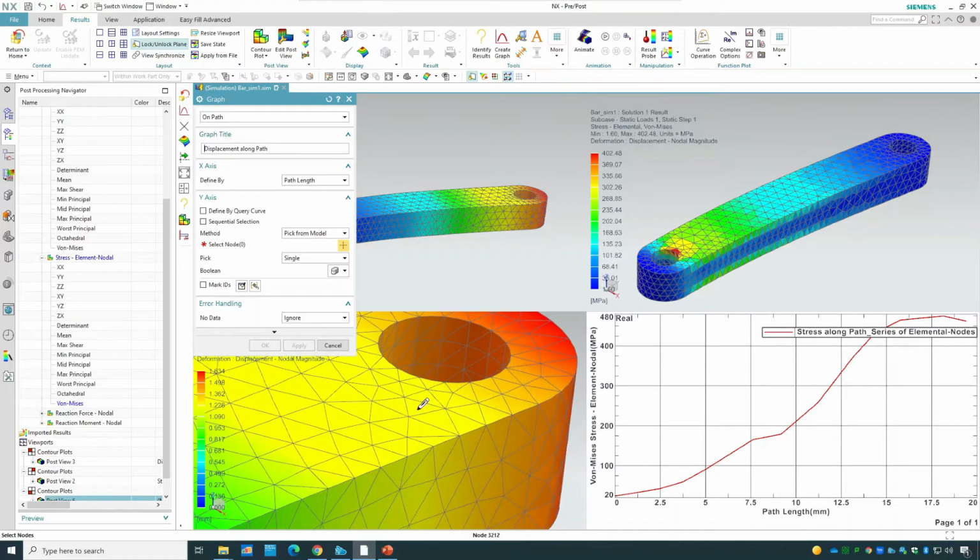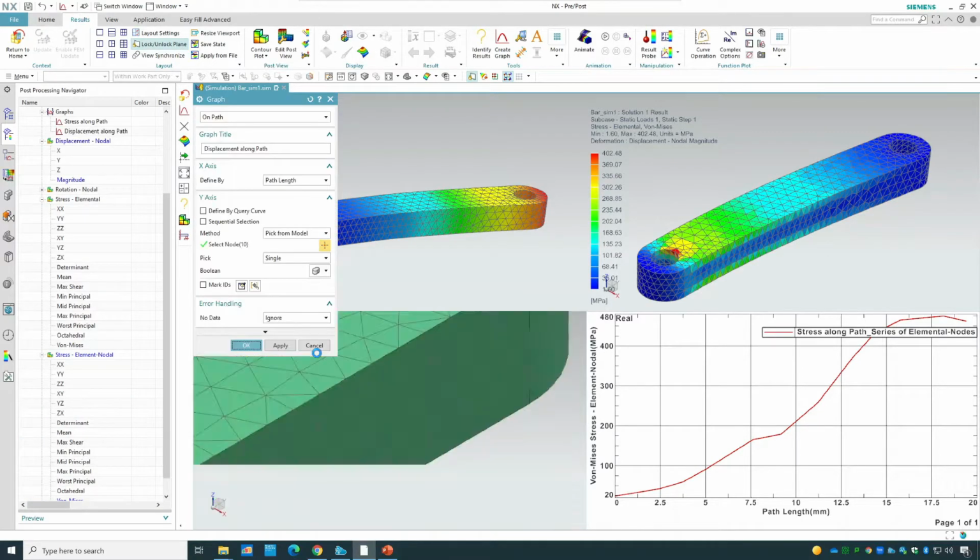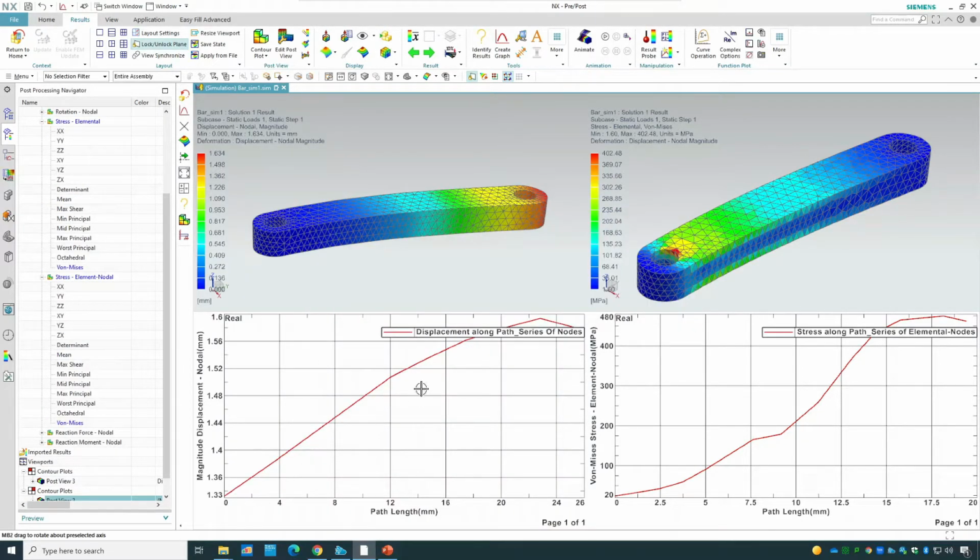I'm going to start from, for instance, this area, that area, that area. I'm going to go for that curve to see what sort of displacement would change. I'm going to click OK, apply there, and you can see, of course, that's the displacement I have. So this is how you are able to have full control. That's a really good and useful way to present it.